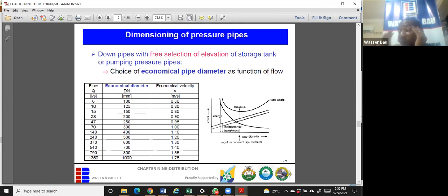If you ask me the depth ratio of a beam, I will say the length over, is it 25 or 23 for a continuous beam. Okay, I'll just say the length over this, and I'll know if that is less than 150 or not. You know, this is what engineers do.